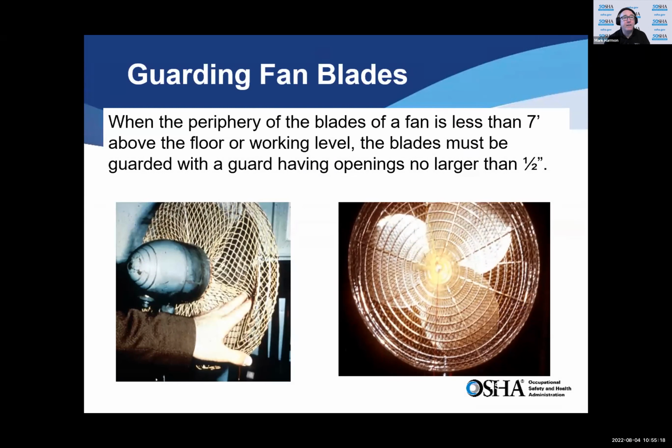Fans, again, we see fans. This is another example, trying to get you prepared for guarding. The particular picture we're looking at says that when the periphery of the blades of the fan is less than 7 feet above the floor or working level, the blades must be guarded with a guard not having openings larger than a half inch.